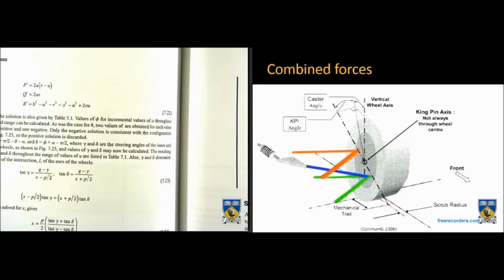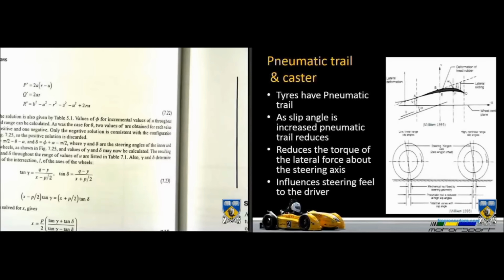And the next bit to consider is our tyre deformation again. A big assumption, that's always wrong, is assuming that your tyre is rigid. That's really not true. Tyres have what we call pneumatic trail, and it's actually a stretching of the tyre contact patch based on the mechanical trail. So the movement between where it's at standard and then when it deforms, you've got a pneumatic trail, and that pneumatic trail is additional to your mechanical trail, and it's proportional to the load on the tyre.